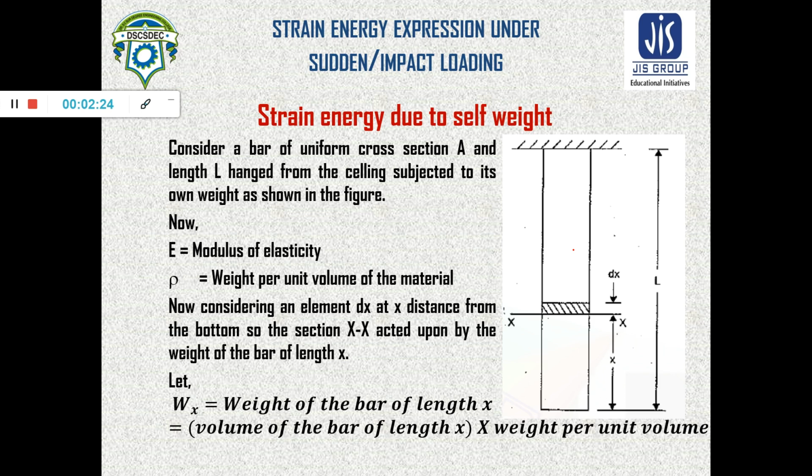we have to first consider a small element dx. Now the weight of the bar of length x acts upon this small portion. So this weight Wx is the weight of the bar of length x, which can be given by the volume of the bar of length x